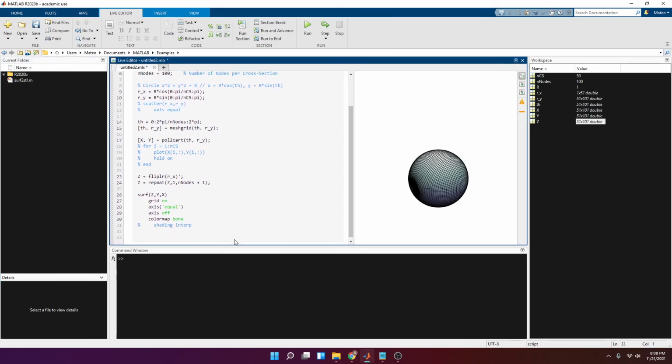And what you do is you call it first, surf2stl, open parentheses. The first argument is going to be the name, sphere.stl, you have to add the extension, and the next 3 arguments are going to be the coordinates. It tells you how many faces the geometry has. That's quite a lot of faces, but it's a sphere, so you want it to have a really smooth curvature.